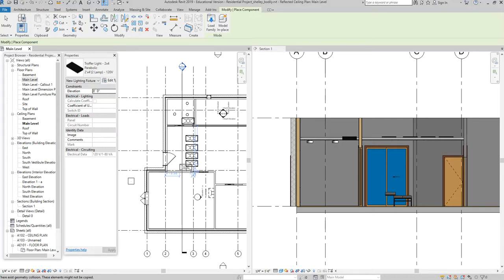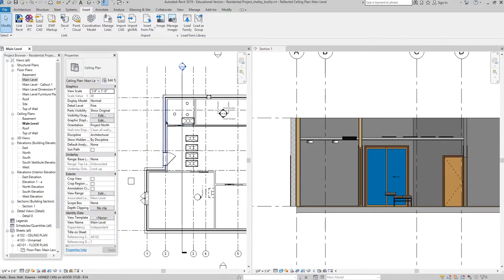Great, we're done. But then when you go to add lights, it doesn't work and you're trying to figure out what's going on, right? So I know it's a pain in the neck. It's kind of an extra step. You have to add something else into your Revit project, but I would always err on the side of, we'll say, caution, because I like things to work the first time, and I like to build my ceiling into my model, okay? So when I'm generating ceilings in Revit, I always create an actual ceiling. I don't place gypsum board on the bottom side of a floor type, okay?